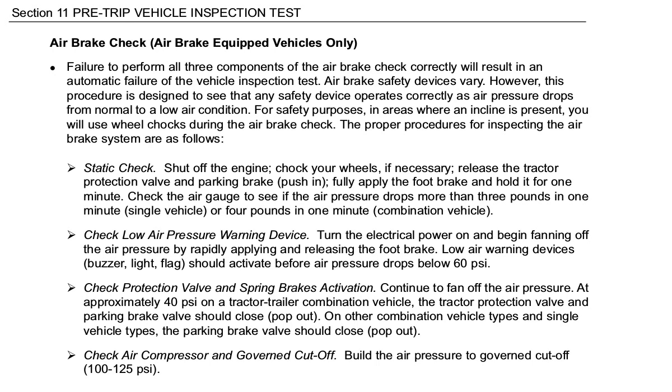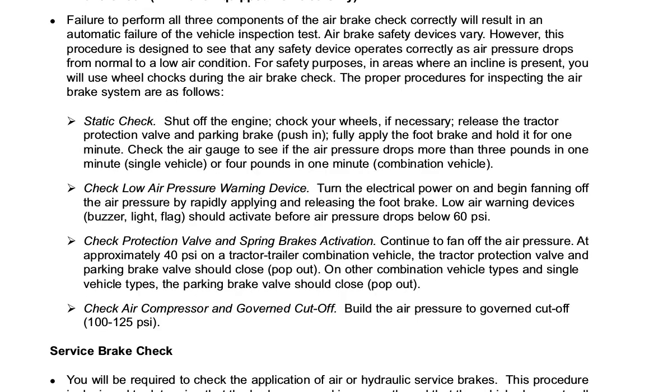However, this procedure is designed to see that any safety device operates correctly as air pressure drops from normal to low air condition. For safety purposes, in areas where an incline is present, you will use wheel chocks during the air brake check. The proper procedures for inspecting the air brake system are as follows.